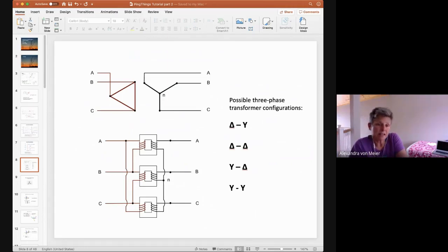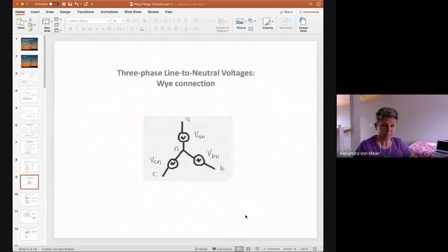And also, if you're making a very high precision measurement, you care about the few volts difference between neutral and ground. But somewhere that neutral is grounded. So we have a delta version and a Y version of connectivity. And what I didn't show you last time, because I said, well, we got to talk about phasors first, is some diagrams of how the three phases in voltage and current relate to each other.